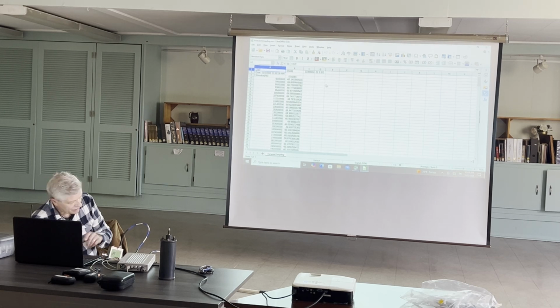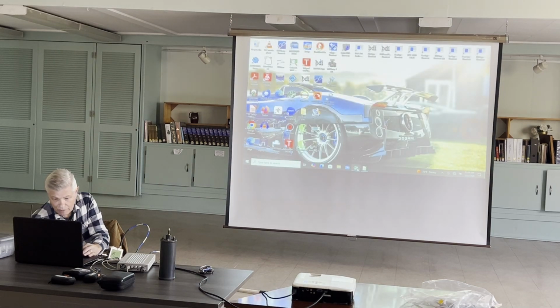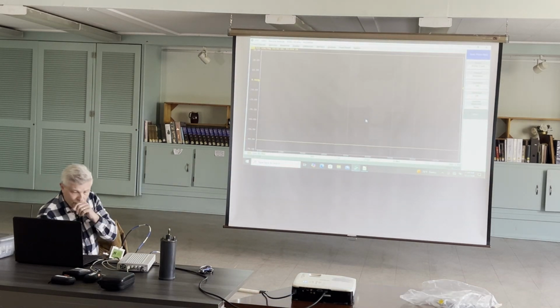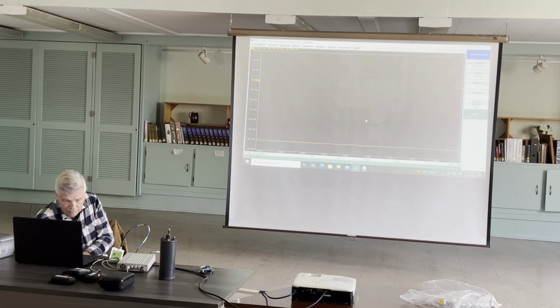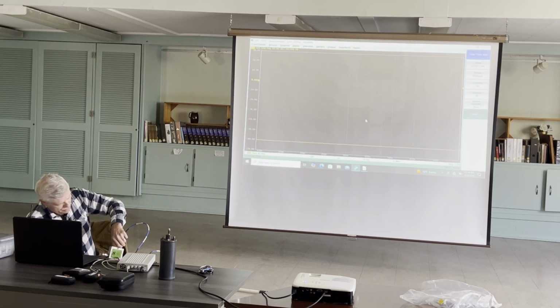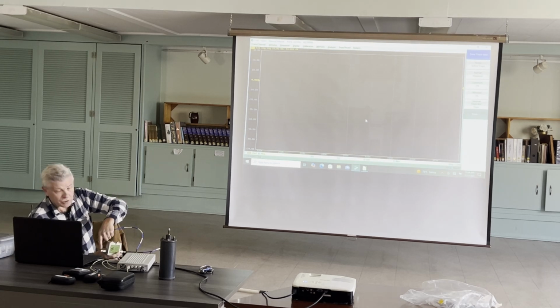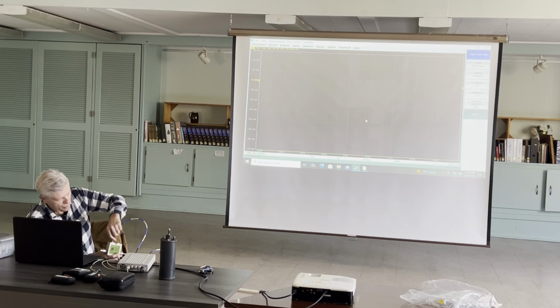Now I would grab the reflected coupling and put that next to this, and that's what we would use to do that. I won't bother with that now, but I will show you. Okay, so remember that this is the coupling, so it's 60 dB down. Now if I want to look at the influence of the incident signal going into this load right now on the reflected port, we should see very little. And again, I've got to move my reference up because it's below.